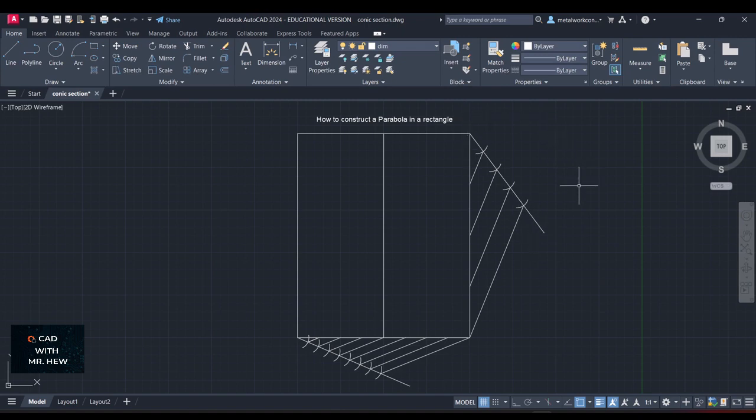All right, on using CAD, you would use a different method. We're just giving the option for those who are using t-square and set square, the traditional instruments, how they would actually draw these lines parallel. So you would use 2 set squares, probably a 30, 60 set square and a 45 degree set square.